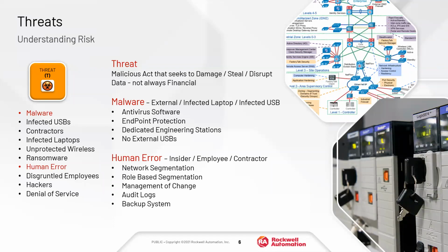When we start looking at countermeasures for this, especially in terms of removing potential human error, we start looking at defining security zones. Segmentation that's not only on system function, but also by role. So we look at operators, maintenance personnel, administrators. A good example of this, when we talk about separation of duties, is your basic process control versus the safety instrumented system, so the BPCS versus the SIS. Typically, those are two different maintenance personnel groups. So different groups, different folks that have to deal with it. You can have different assignments so that one does not have access to another.